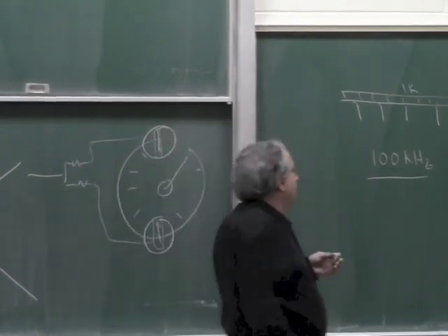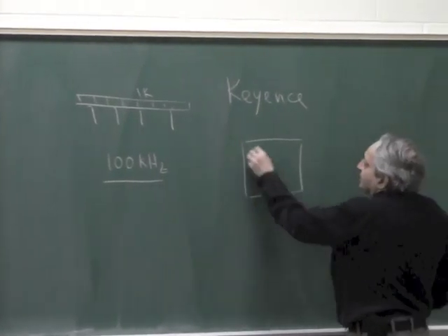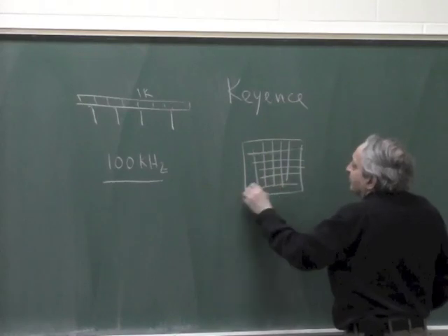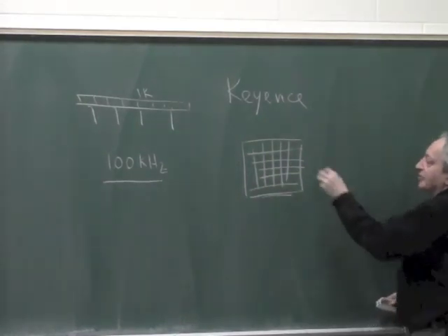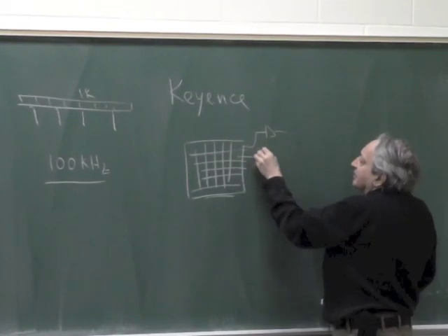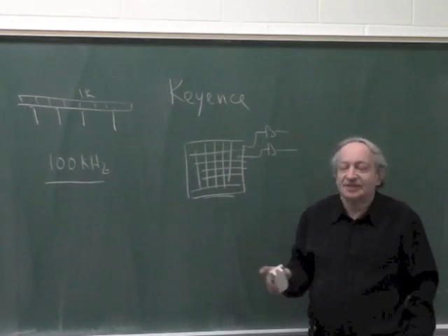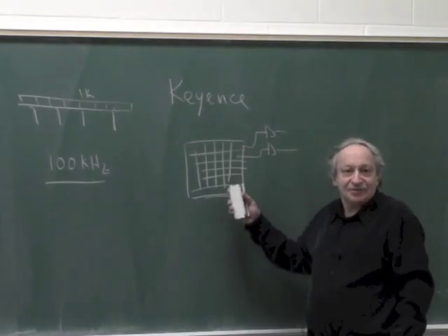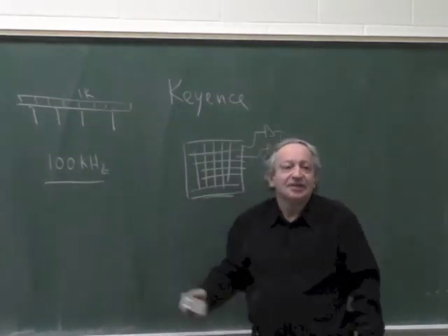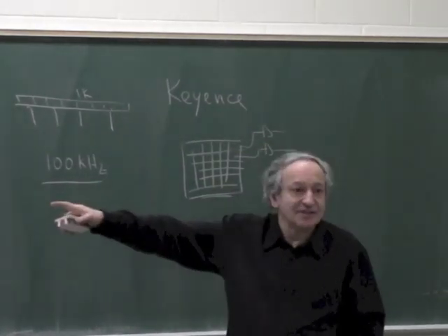Let's say you want to build a custom chip which has 100 by 100 sensors, so it's 10,000 sensors, and you want to bring each one out with its own amplifier. So this will operate at the same speed as a single detector. So in commercial chips, I would say that's the limit for linear, and maybe 1,000 hertz is the limit for arrays in commercial chips.